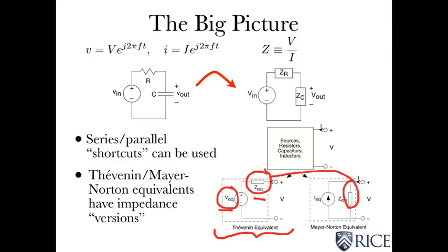The two impedances are the same, and that's the amplitude of a current source, and that same formula applies that we derived, but for impedances. The amplitudes of the equivalent circuit obey this relationship, and that's the equivalent impedance. So there's no real surprise there, and you can now use these equivalents in RLC circuits just like we did for resistor circuits.